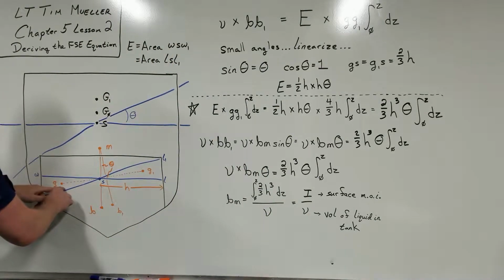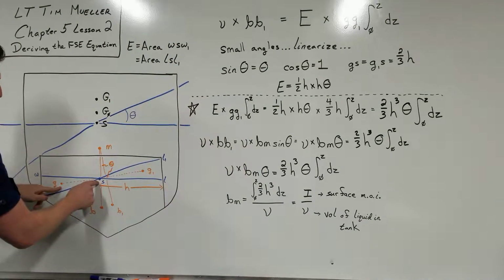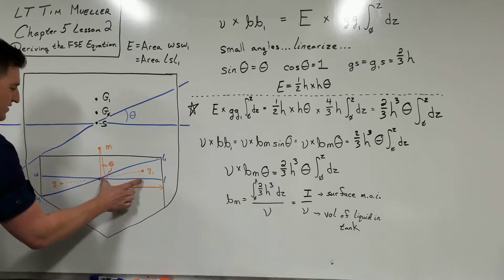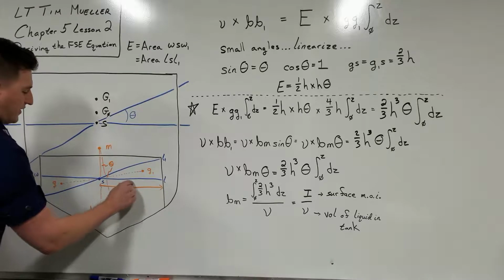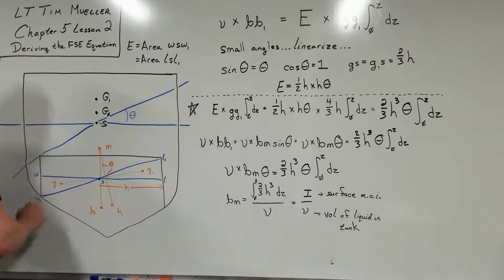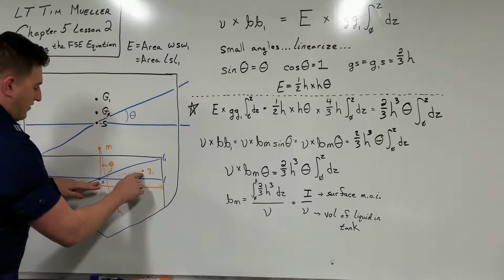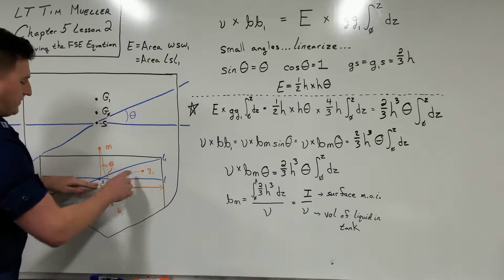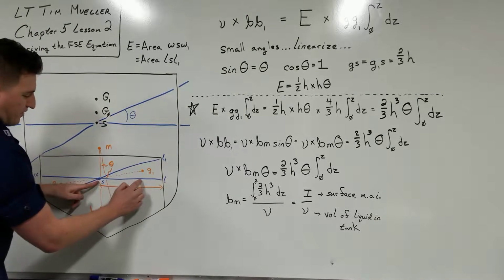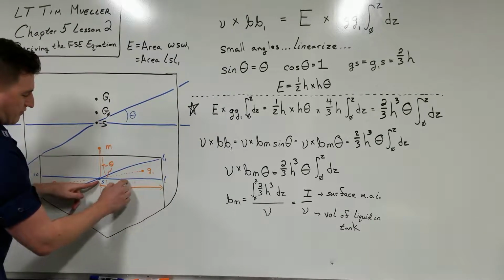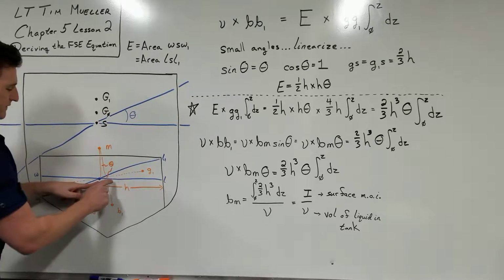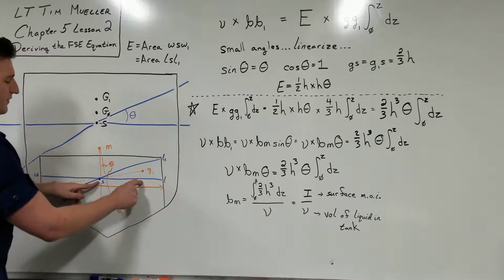The center of gravity moves here to here, and it kind of pivots off of this point here, S. Now we want to find this horizontal distance, S to G1, which is the same as G to S1. If SG1 is the hypotenuse, then this distance, to make this right triangle, is going to be SG1 times the cosine of theta.